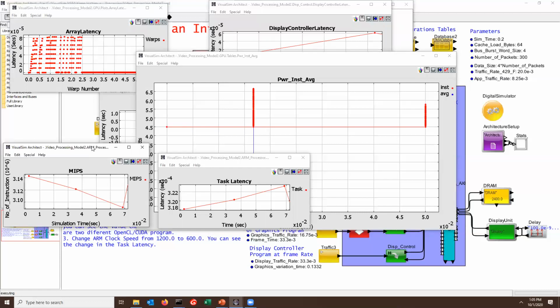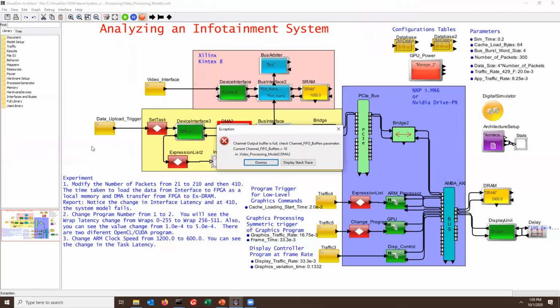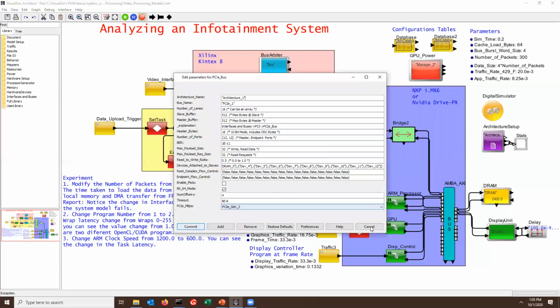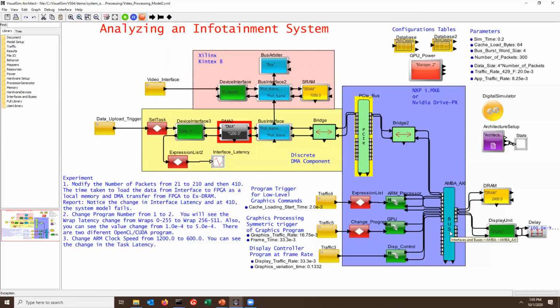As you can see now that I've made more of these parallelization, I'm actually able to run a little more, but again, it looks like it's a band-aid. It's not a fix. So I really have to change other things. So then I have to look at, do I change the PCIe? Do I change the AXI bus? What do I change to get better performance?